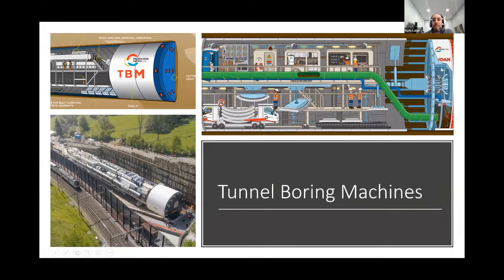But the advantage of them is that you have this one machine where it operates 24/7. It drills out the ground, conveyors out the dirt. They can bring in tunnel lining, and it supports around it. So 24/7 a day, this drill head is advancing, and people are lining the tunnel and such behind. So the tunnel gets built behind it as it goes.